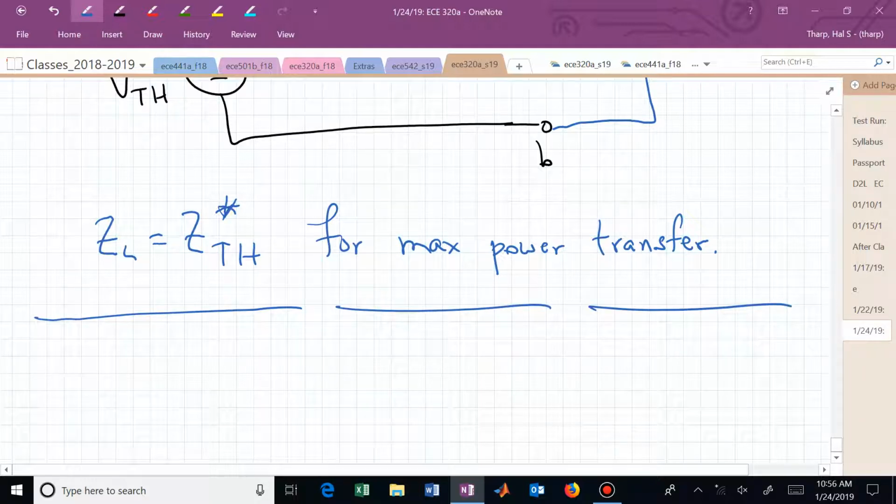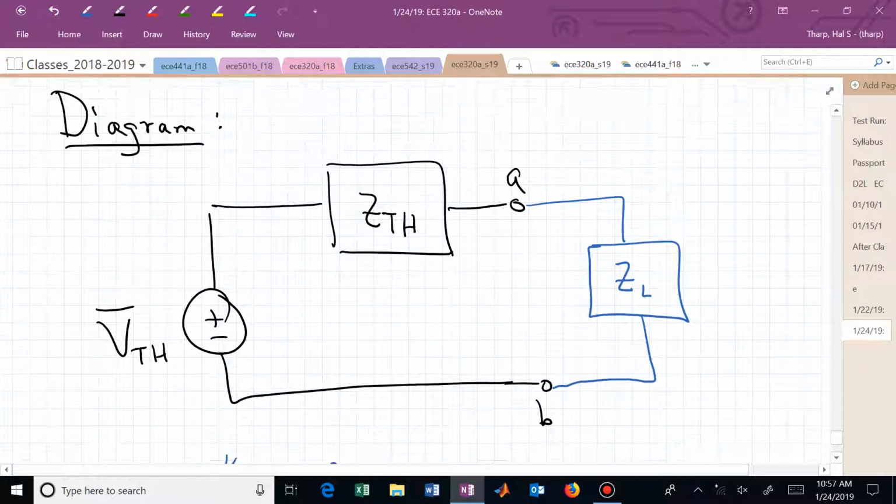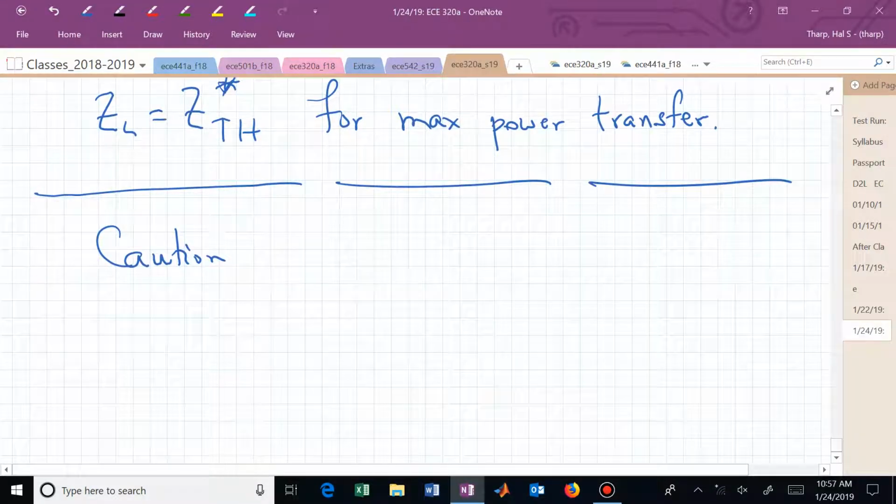Now it actually might be a good time to sort of caution you when you're dealing with power and you're trying to maybe analyze a circuit and you want to maybe do some Thevenin equivalence in the analysis. Well, back off a little bit because there is a caution. Thevenin equivalents really are only useful for creating similar electrical conditions, currents and voltages at the terminals.